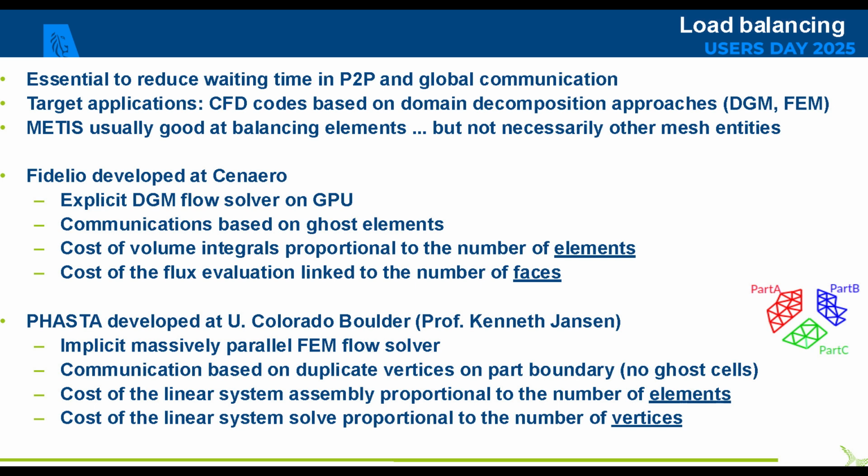but the cost of the flux evaluation, and I encourage you to see again Orient's presentation, who did a nice work to explain how it works, the cost of the flux will be proportional to the number of faces or interfaces between elements. So it's important to balance both of these entities, and usually you get only one. Or there is a risk that you only get one.